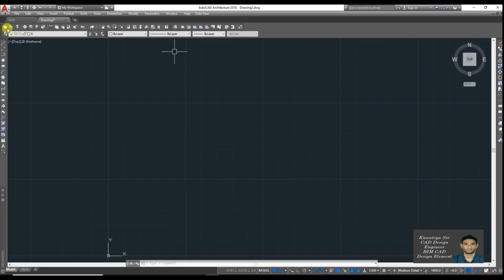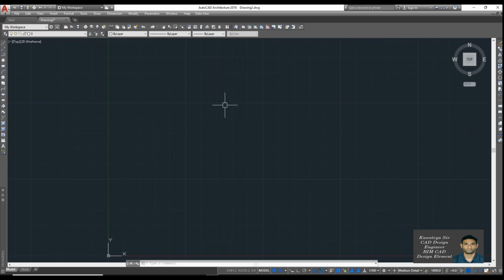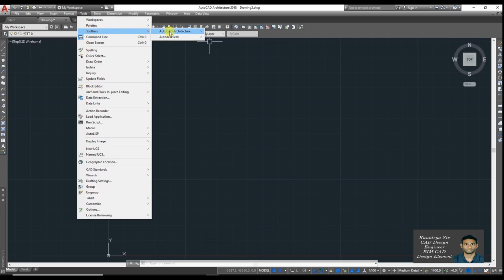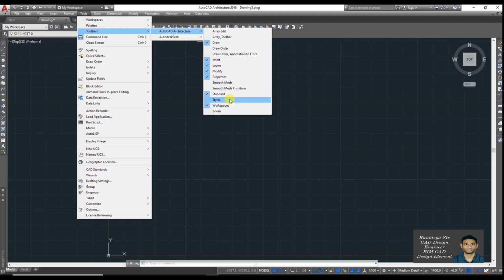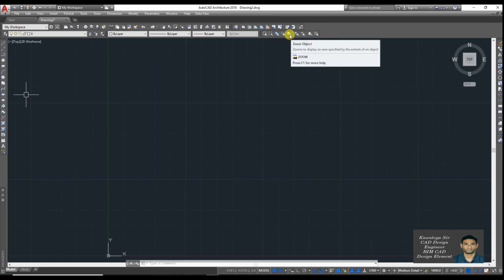Here we get the Save and Open options available. Then go into this and we can get a Workspace toolbar. So it depends upon which project you are using and which kind of function you need. Sometimes a toolbar just pops up in the drawing window. You can simply select it and drag it to the location where you want to place it. And this is how we can set up our AutoCAD Classic Workspace.